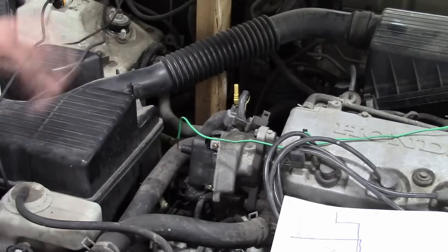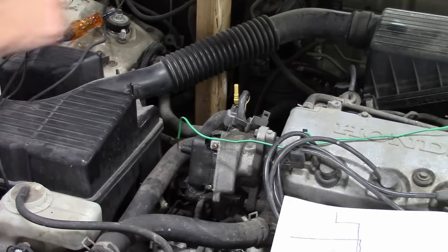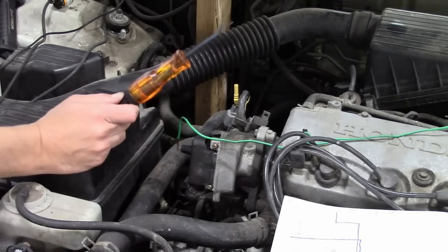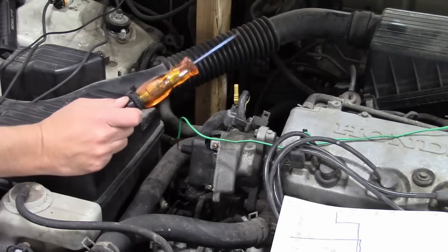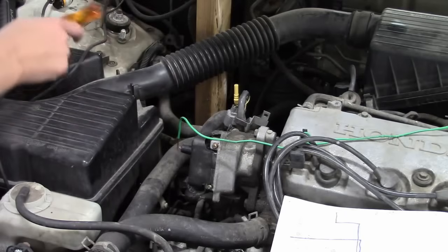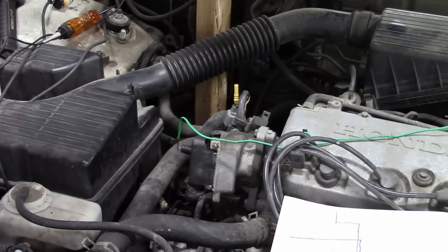All right, well, it did look to me like that was flashing, albeit fairly rapidly, and it was a little hard to confirm 100% that it was really flashing because it didn't seem there was time for the light to go out all the way. But that did seem to be control to me. Again, another reason why a scope would be so helpful. That may have been a little inconclusive. A square wave on a scope would be 100% definitive. And I think at this point, that may be where I want to go next.